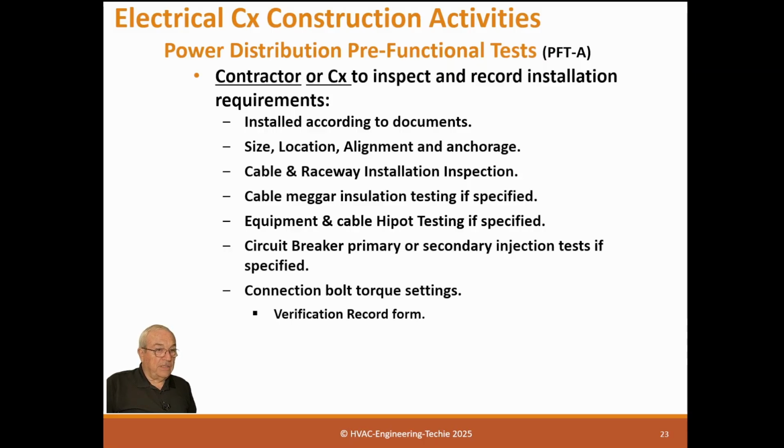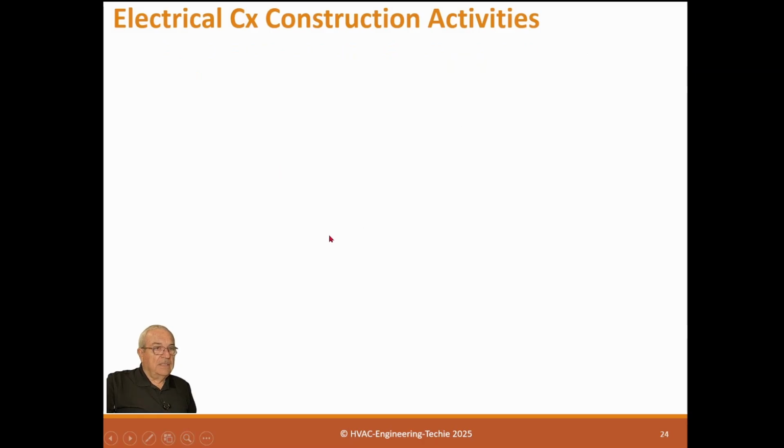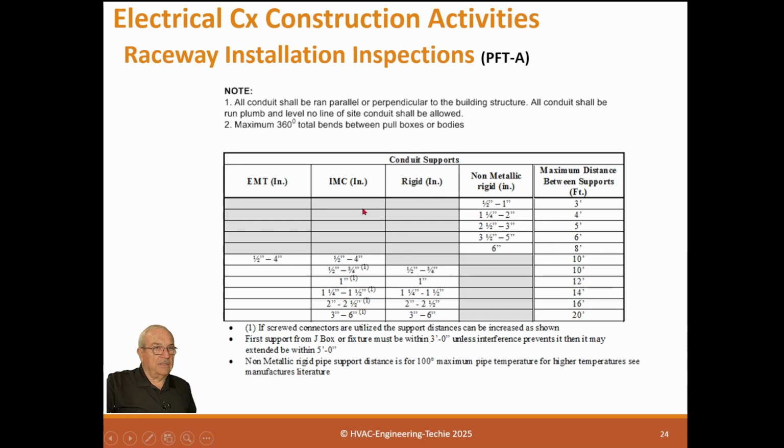Once it's torqued to the right value, he marks it through the bolt, the nut, and the plate, so you know it hasn't been moved. If someone comes by and moves it, that line will not be together, and you'll know right away someone has moved it, so then you'll have to call for a retorquing. So there are some things you can't check again.